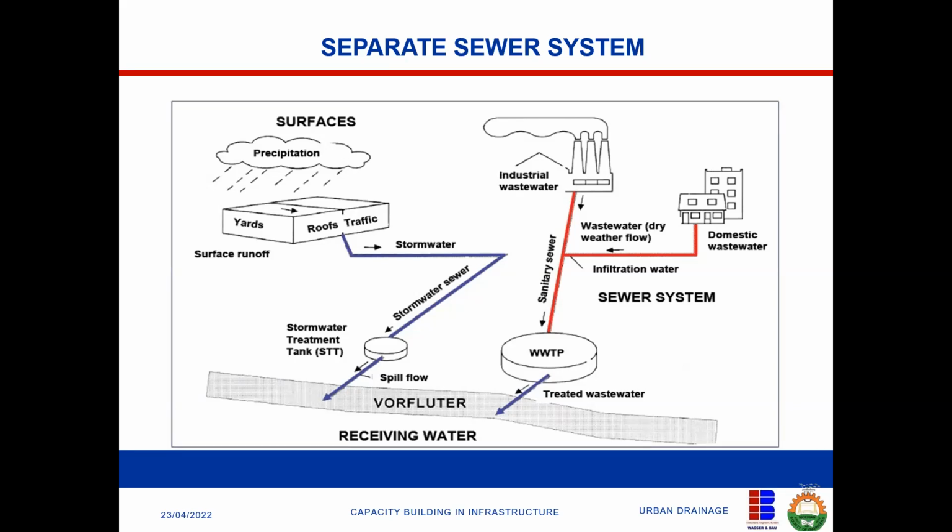Those of us who are into wastewater treatment know that the commonest method of treating wastewater is what we call the aerobic system, or the activated sludge system, where you make use of bacteria. You build a medium, and you build some level of bacteria within the medium. So once wastewater comes, those bacteria will eat it up and excrete carbon dioxide. They will be eaten off, and so the water will treat itself.